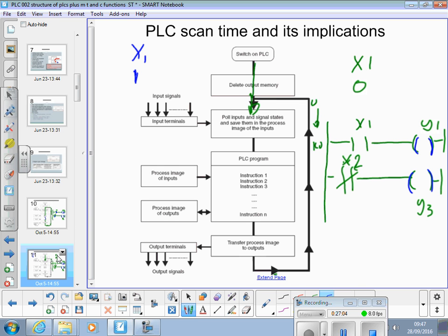There's also, if that switch turning on is just after it's done that poll, it's got to go down through the program, even if that's a permanently on long signal, it's got to go down through all the program, back up to the top, pull them inputs again, and go all through the program again, virtually 2 full scans before the output turns on. So there could be that much inherent delay in a signal being made and the output reacting to it.